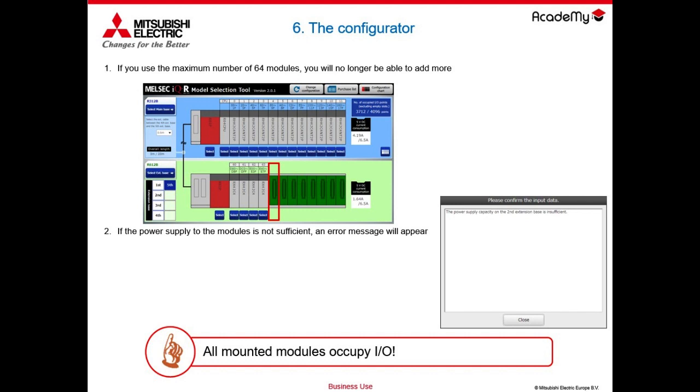So as I said, the configurator knows all the rules of configuration. If the power supply of a module is not enough, an error message will appear. In this case, on the second extension, the power supply capacity is insufficient. For an error of this type, what can you do? You can choose a larger size power supply, if it has not already been done, or you can add a larger size power supply to the added rack.